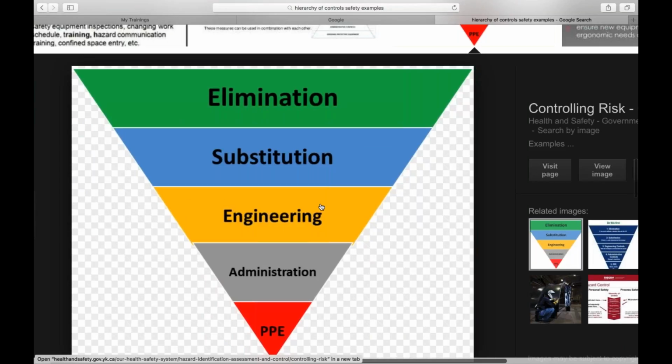The main thought we should be taking into consideration is an engineering control. Basically, how can we engineer out a hazard? How do we engineer it out? Normally, we either substitute the material for a less hazardous material, or we eliminate the hazard altogether. A perfect example is asbestos insulation on pipes in a refinery. Well, what are we doing? We're going to use an engineering control.